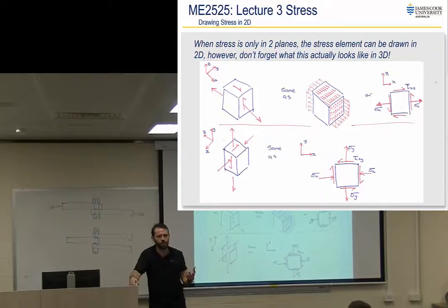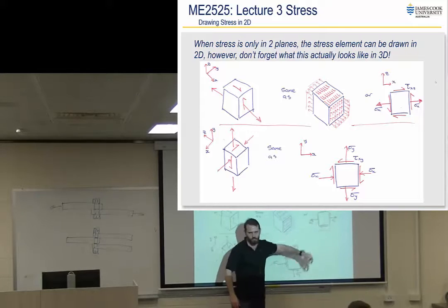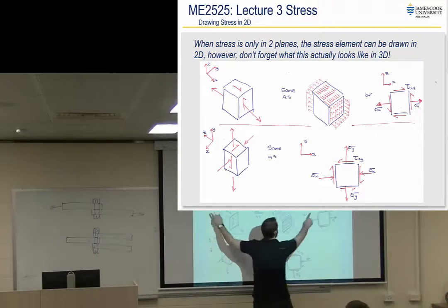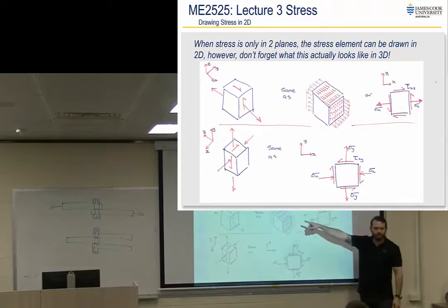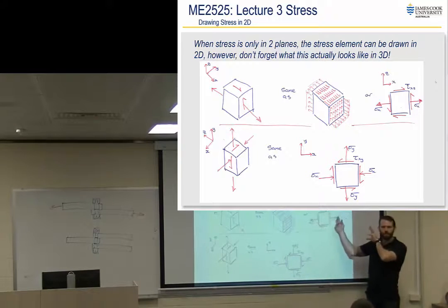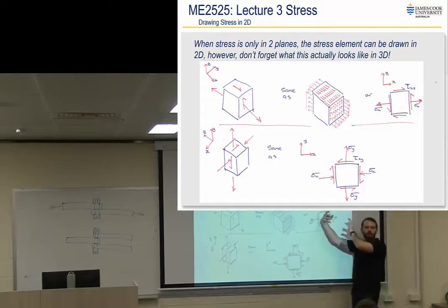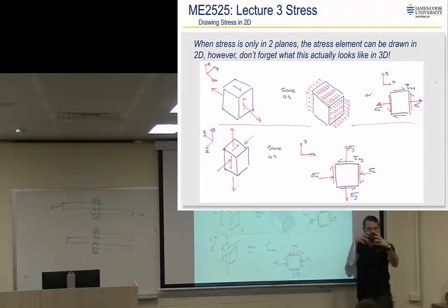All right. If I had anything in the Y direction, then that would be 3D, and I can't, in that case, condense it down to one of these representations. But almost everything that we deal with in this class, we'll be able to boil it down into a 2D representation. Now, the important point here is 3D Cartesian coordinate system, 2D Cartesian coordinate system that matches it. I've rotated it down to my 2D space. Once I calculate these, I might actually need to transpose this back onto the machine component drawing so that I know where the failure is going to occur, perhaps on what plane. So you need to keep that, and then you need to be able to physically interpret that back onto the plane. All right, so it's once again that 3D rotation in your mind that will become quite important.